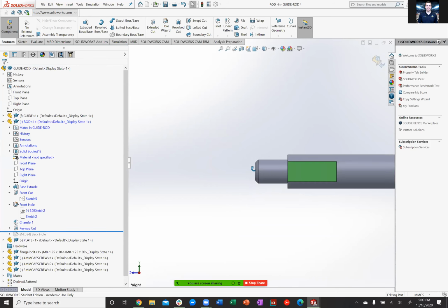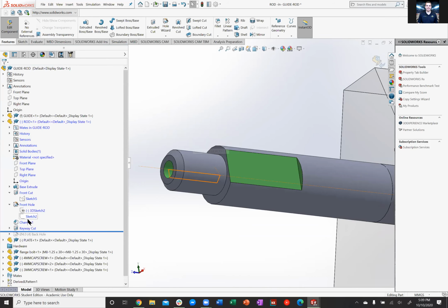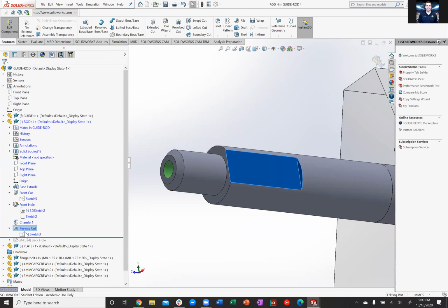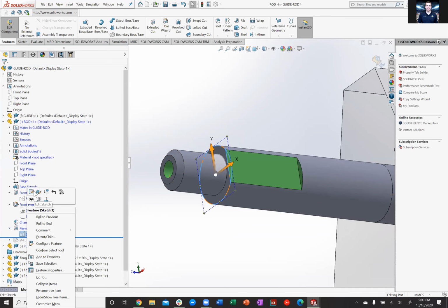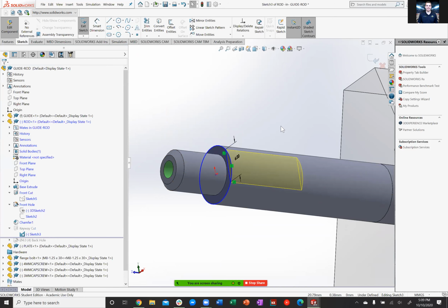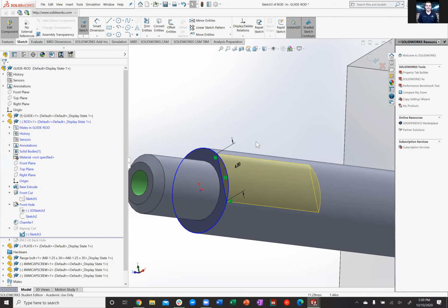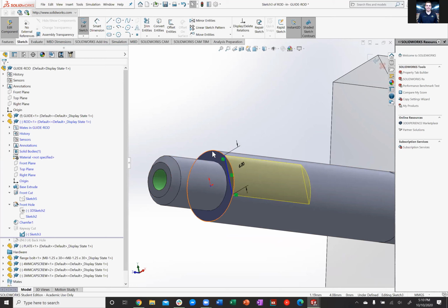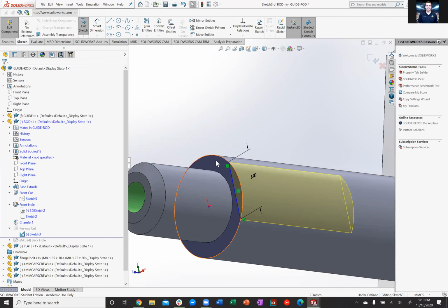Next, we did a keyway cut. So to make this one, let's open Sketch. Making flat features on a round part can be tricky sometimes, but luckily for this one, we still have some flat planes to reference off of. So you make your new sketch and then you reference a flat plane.